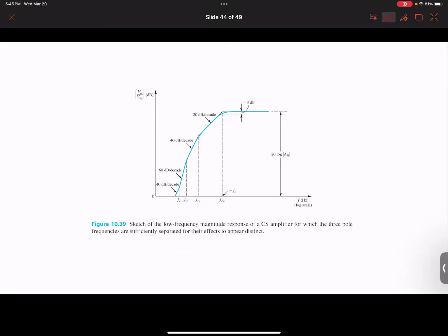So typically, you see that this P2 is due to CS. This P3 is due to CC2, and P1 is due to CC1, and FZ, of course, is also due to CC1. So that's how it works. And then that's your log frequency response. And it's always in the form of S plus omega Z and S plus omega P. So this omega Z, it could be 0 or non-zero, that's fine. So it can be both.